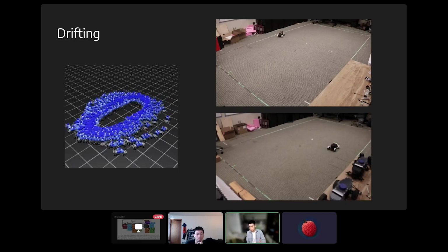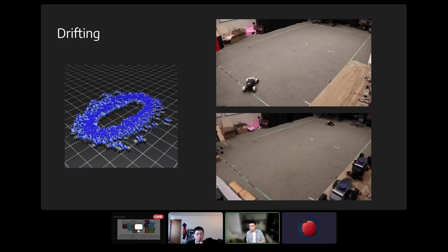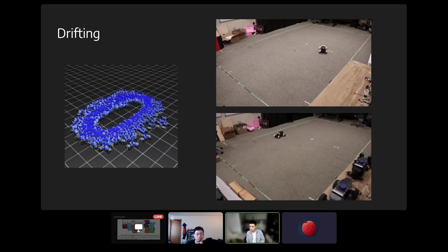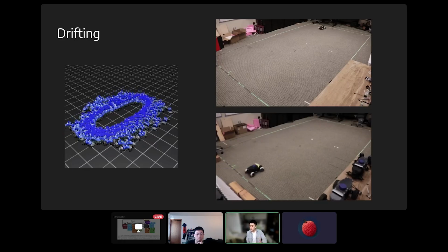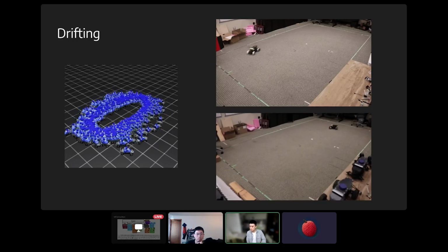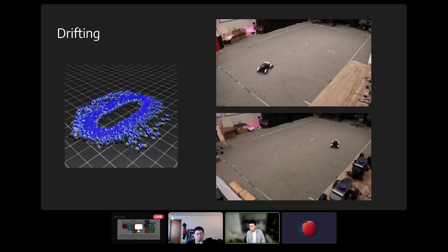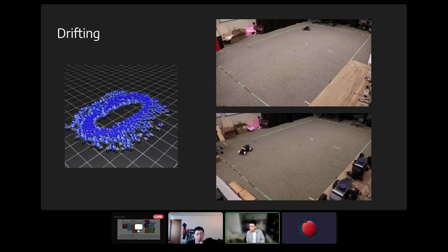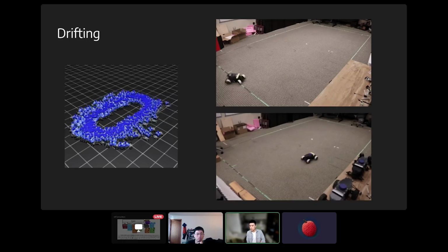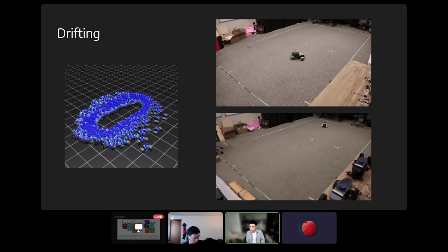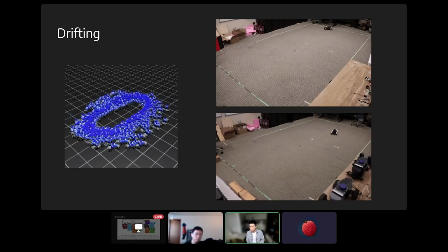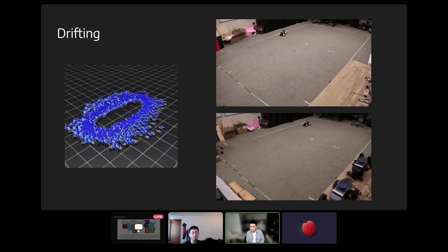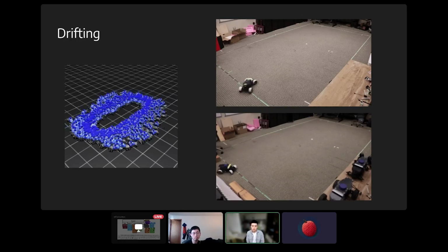And also when you drift or when you hit the throttle quite aggressively, it shifts the weight due to the suspension onto the vehicle. Normally this isn't a problem, but for tasks that are quite dynamic, these small changes matter, especially when you're running at 50 times a second and you're trying to perceive changes in your state and adjust accordingly.